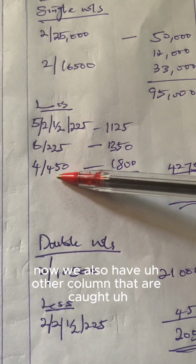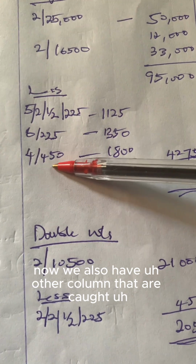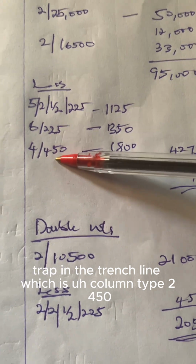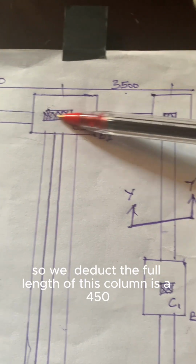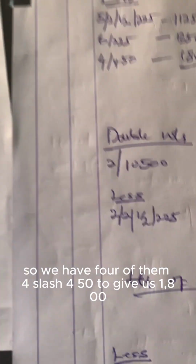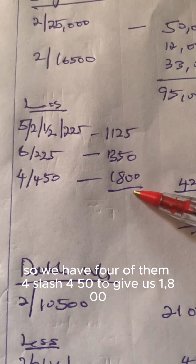Now we also have other columns that are trapped in the trench line, which is column type 2, 450. In that case, we are talking about this and this. So we deduct the full length of this column, which is 450 this way, 450, 450, 450. So we have 4 of them, 4 times 450 to give us 1,800.